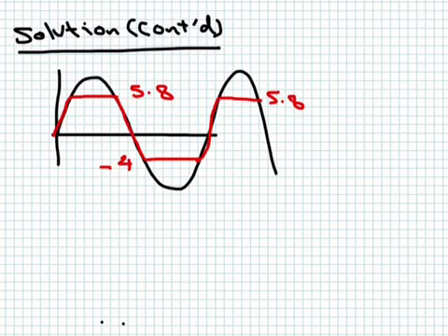The easiest way to solve problems with diodes or Zeners: assume a region of operation, try to verify it, and see whether it makes sense or not. If you get a contradiction, then the diode or the Zener will be in a different region of operation. If it works well, your assumption is valid, then your circuit analysis is correct.